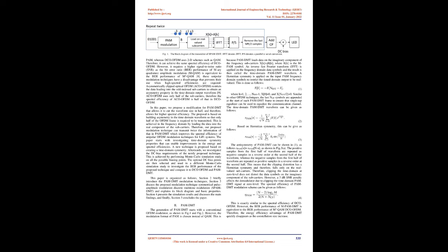However, the addition of the DC bias results in an additional power dissipation that is not directly used in information transmission. Several different modulation techniques have been proposed to address the problem of spectrum efficiency in conventional DC-biased optical OFDM, DCO-OFDM. Unipolar OFDM techniques attempt to use the properties of Fourier transformation to adjust the output of the OFDM modulator.